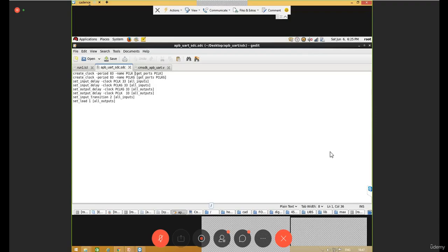I just told you there is an NLDM lookup table. The tool is automated in such a way that whatever transition value is suitable for optimizing your timing, power, and area, that process is taken care of by the tool. Which delay value it has to pick is done by an interpolation process. It's a tool automated technique. As a user, you should not bother about such things. We are just giving input that you need to take in this particular range of values according to the library. Okay, thank you.